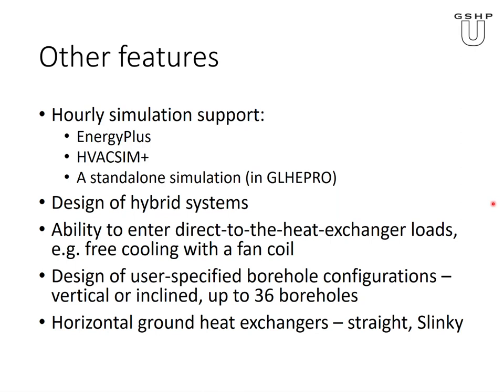Okay, so GLHEPRO, it supports simulations with EnergyPlus. Maybe I should say it supported simulations with HVAC-Sim Plus. We used to do a fair amount of simulations with HVAC-Sim Plus and don't use it so much anymore, but it can output the G function in a form that can be read, at least by our HVAC-Sim Plus interface.